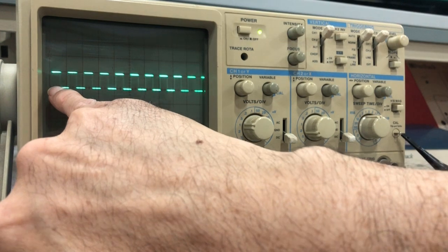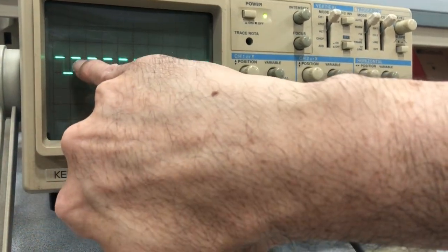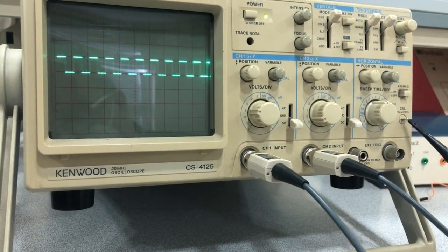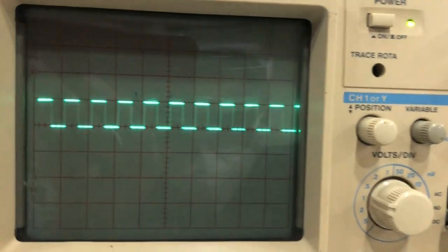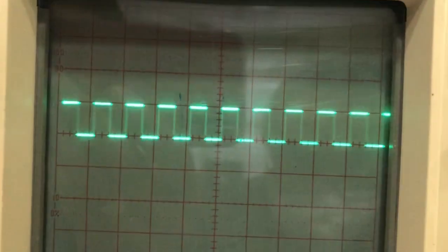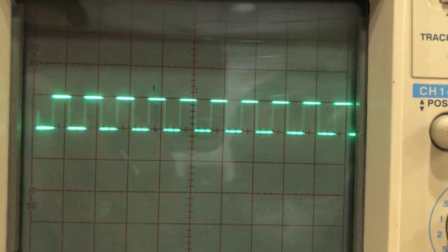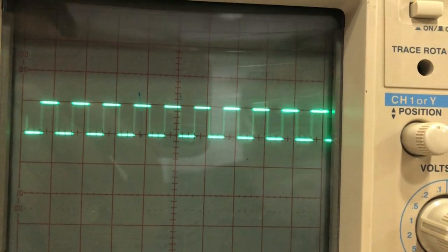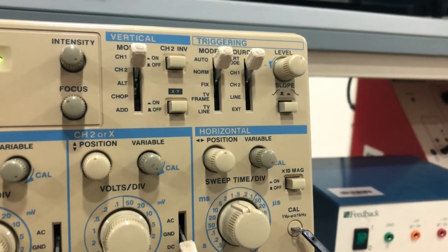Notice now that the positive slope is going from zero to high, but I don't see it clearly on this line because the rise is very fast. It's very dim, and I don't know if the camera is showing it when I removed my finger. So it's plotting from the positive slope of my signal. If I want to start with the negative slope, I push it in, and it starts plotting as the signal goes down from 1 to 0. So now we understand the level knob of triggering, and we understand how to start plotting from the positive or the negative edge.